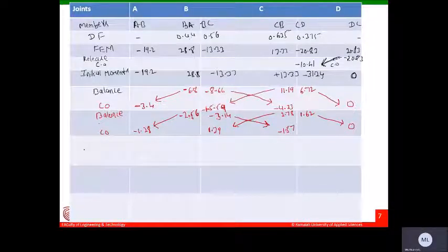Okay, this is carryover. Next we can do another trial. So this is balance. Now once again I need to do the balance. Here we got 1.39. So the summation of the movement at the intermediate support is multiplied with the distribution factor, change the sign, write down the values. You do it: 1.39 into 0.44. How much will you get?